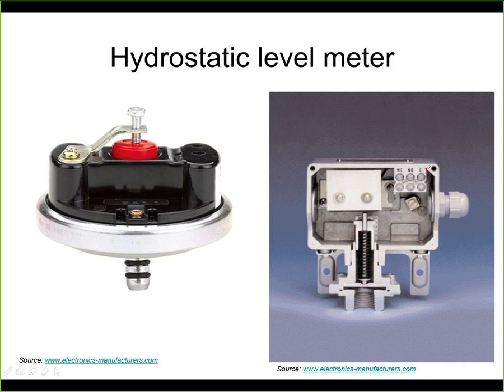Judging by this description, this terminal box, this looks like it's a liquid level switch. So point level measurement, because here we have normally closed and normally open and common contact. So it looks like this is a binary output. It will be used, for example, if you want to fill the tank and you want to stop the pump when the tank is already full. This will get detected by the sensor, and it will turn off the pump.